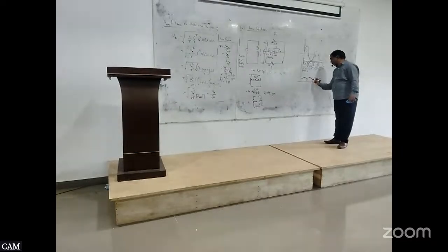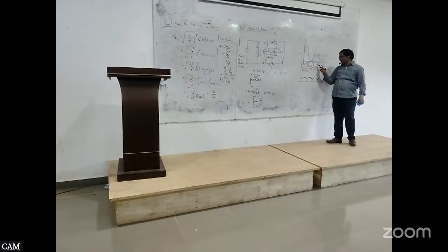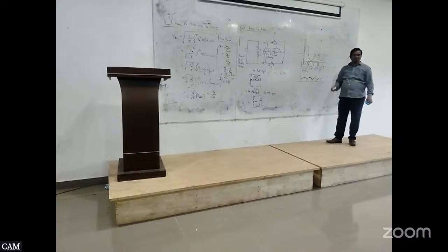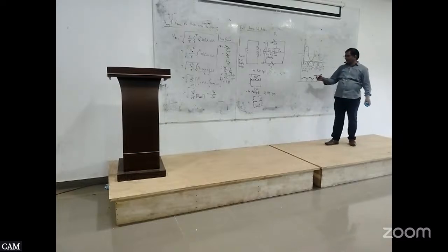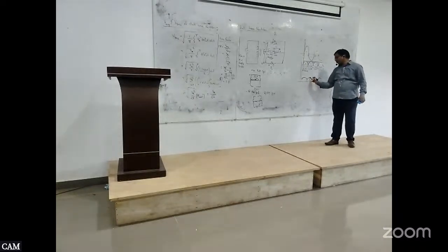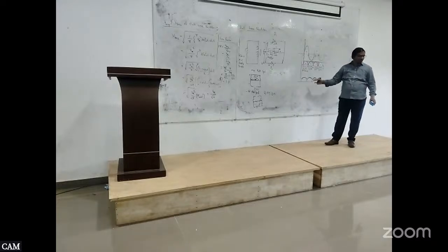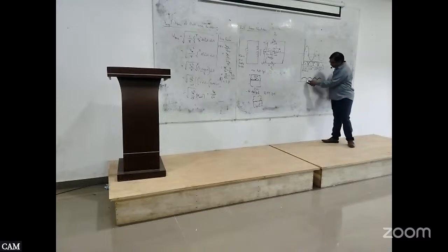Without the capacitor it goes towards 0; at this point it is getting 0, at this point it is getting 0, at this point it is getting 0. But by adding the capacitor, we removed the ripple content. So it is not going to 0 now. No, it is not getting 0. Here also it is not getting 0.